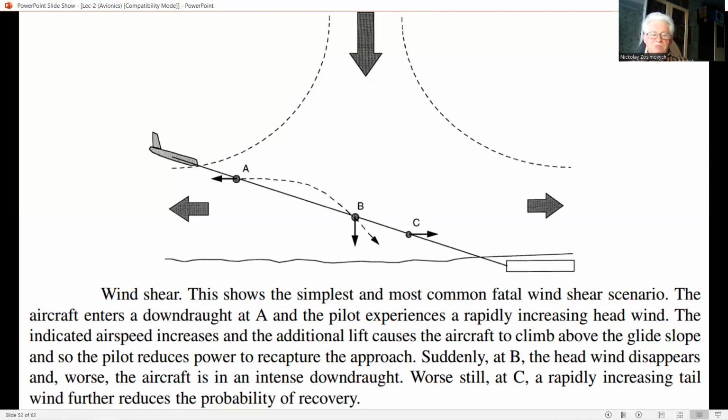The HUD is used to monitor the automatic landing system and to enable the pilot to take over on aircraft which are not equipped to full Category 3 automatic landing standard. Third, use of the HUD as part of an enhanced vision system to enable operations in lower weather minima at airfields not equipped with automatic landing aids, ILS or MLS.